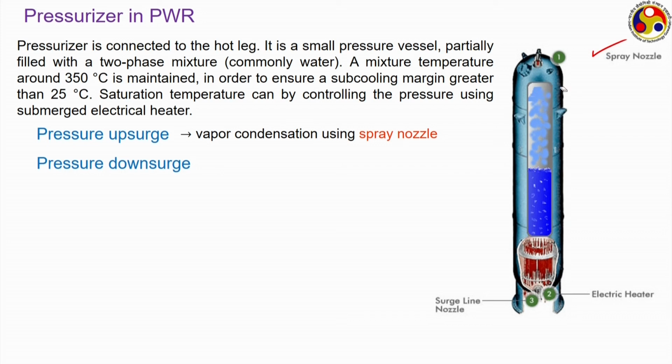So, this vapor will try to expand, but as the pressure has fallen, both liquid and vapor part remain at the saturation temperature corresponding to the initial higher pressure. So, some liquid from this free surface will try to evaporate and occupy that portion, thereby gaining an equilibrium in terms of pressure.